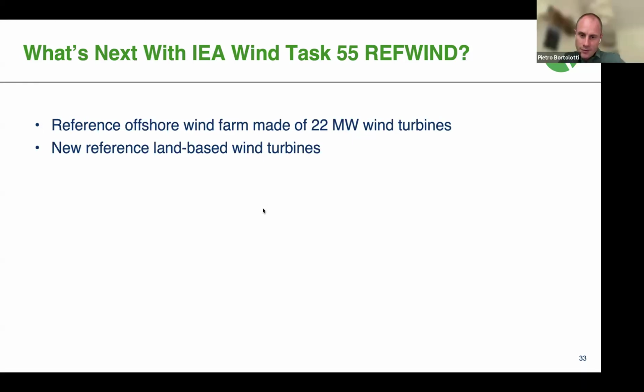One question for you, Frederik, from Francesco Papi. How were the blade geometries designed for CFD? Did you start from WindIO or from anywhere else? Yeah, so we have an in-house Python-based tool that we use to loft the blade. We take the WindIO definition of the planform and the base airfoils, interpolating these to loft the blade. And then, of course, for CFD, we need to make a watertight surface with a given topology, which is handled by this in-house Python tool.